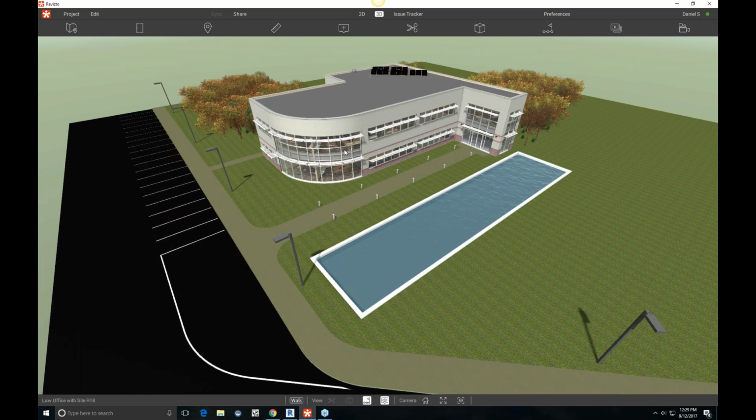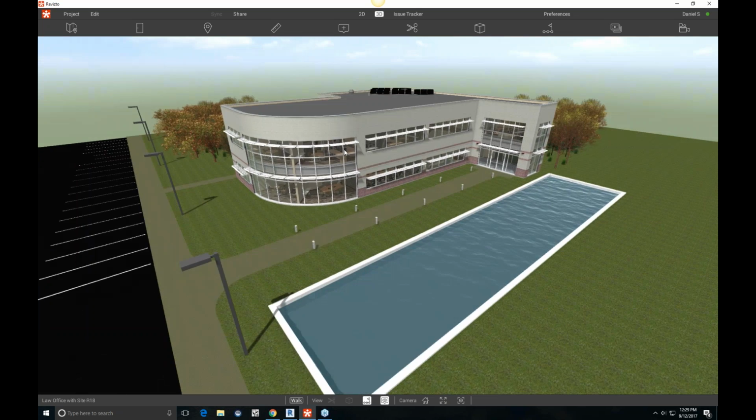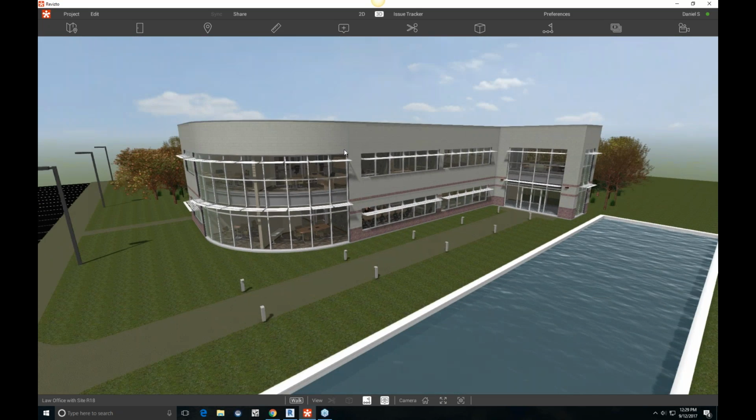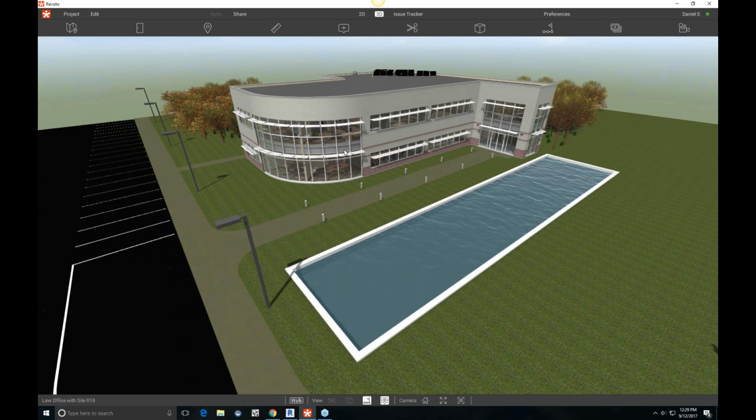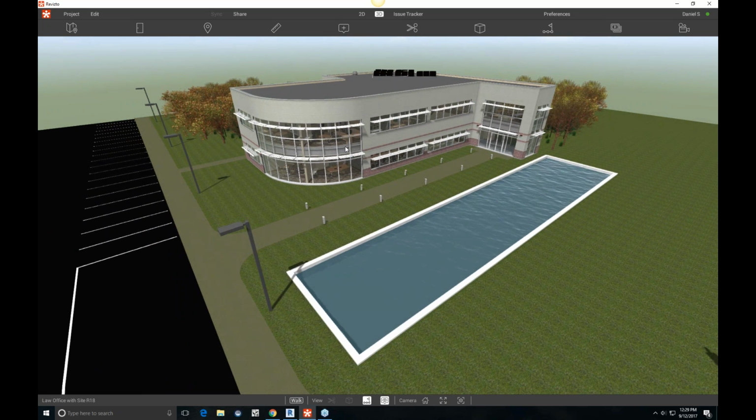The very first thing, which actually can take quite a bit of time, this might even be like an overnight kind of processing thing depending on how big your project is, but you can see here that there's no light sources visible, and the default with Revizto in the viewer is no lights are on. There's an edit button in the upper left, and we can switch into edit mode. So this opens what's called the Revizto editor, and in this mode there's some helpful last minute material changes you might need to make without having to go back into Revit and export.